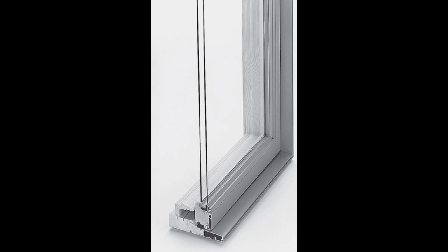Alternatives to this problem are short lengths of defect-free wood that are finger jointed and glued together. While they do provide a solution to decaying wood, or wood that is not as strong, they are not that attractive, so they're often covered with wood veneers on the inside, and then plastic or aluminum cladding on the outside, in order to appear visually appealing.